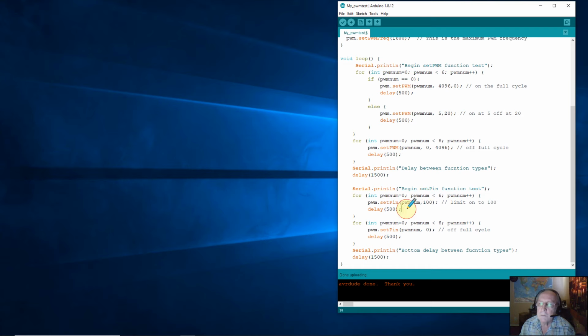And then I do my typical delay. I delay half a second. I set the channel to 1 and do it again. 2, 3, 4, 5, and 6, just like we were doing up here. But I'm not playing with all these double numbers. I'm just sending it a simple value. And then once I've done that, I come back down here and I say if it's less than 6, go in and set pin, channel number, and set it to 0. That turns it off. Delay for half a second, and you see I pulse through them all and I turn them all off.